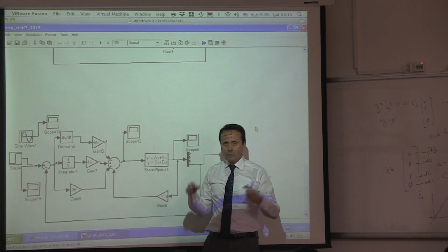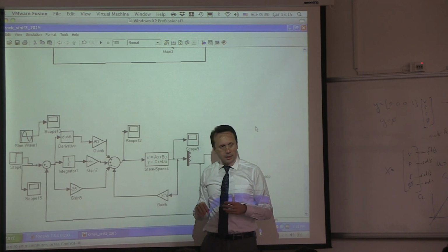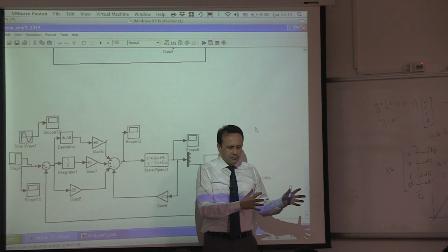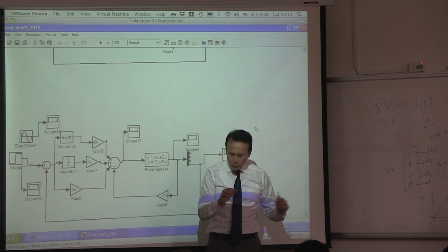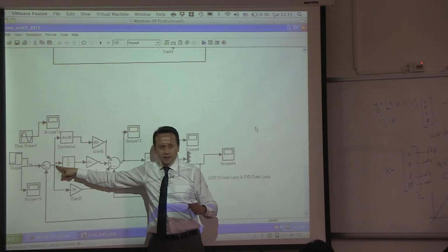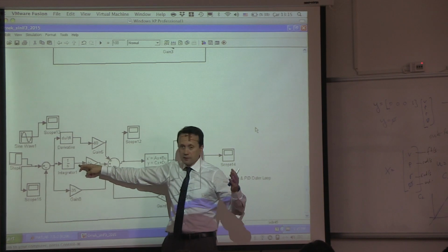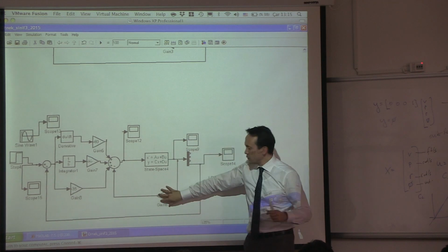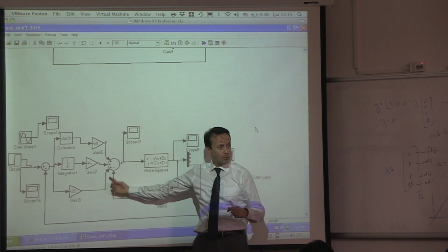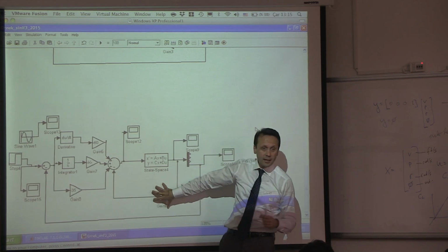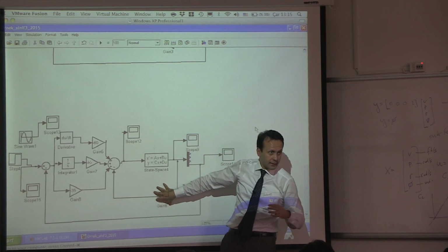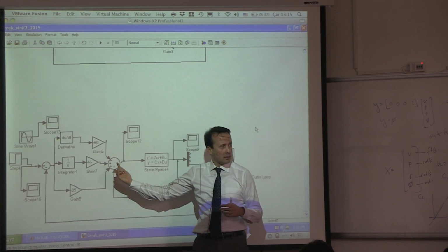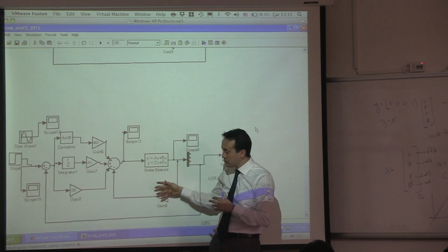All right? So what you're doing in this class, in PID, you do a similar thing but in a different way. Okay? That's one. Two, PID requires one single input over here. And our integral required one single. The tracking required one single input. Okay? But when we design this one here, I get the full state feedback and send it over here. And this is not PID. You cannot learn this. This is modern control. That's why we call this full state feedback control. You get a lot of numbers over here, send it over here.